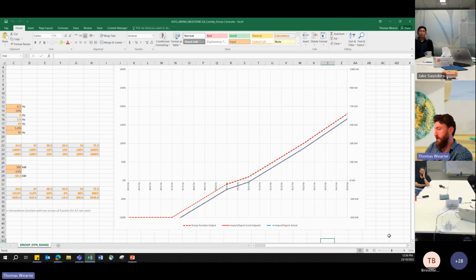But basically, the site detects the frequency, it adjusts the set point, and the inverters will respond as soon as they're able. In my understanding, solar and battery inverters aren't really all that different. It's just a question of how bulky is the DC supply of power that would govern that operation. But they can adjust their output very quickly. It's very easy for me to demonstrate by just making the ramp rate as fast as possible and changing a set point.